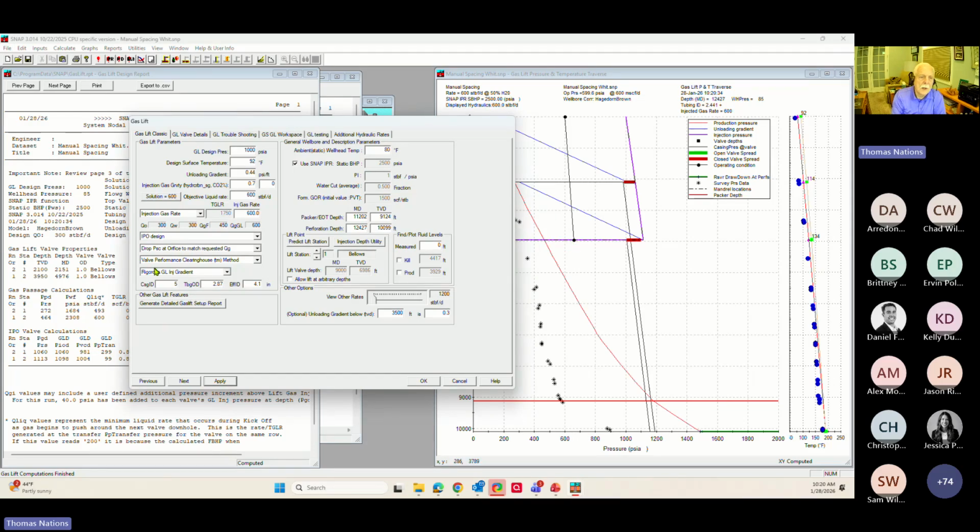The next thing here is gas lift valve performance methodology. There are 3 available selections. Thornhill-Craver, for live gas lift valves, you should never use, because a gas lift valve is not a square-edged orifice in a meter run, which is what Thornhill-Craver calculates.